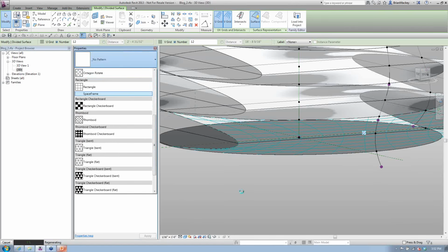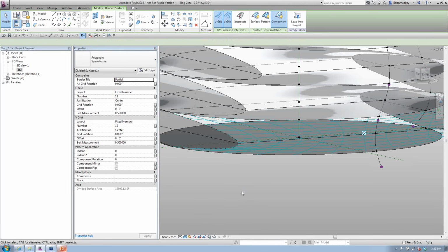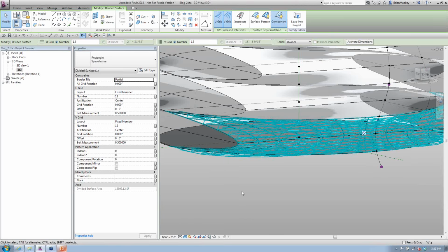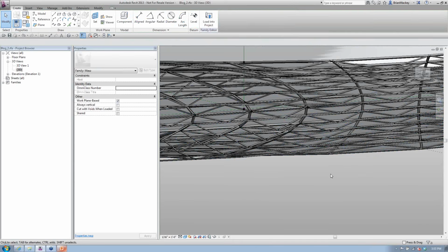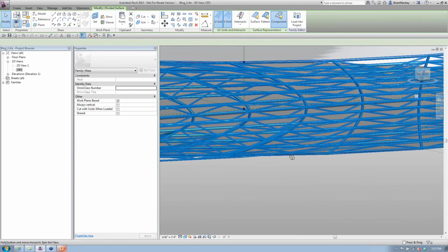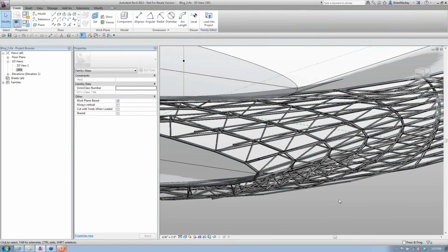So in this case, it was working with a structural engineer, and they were trying to figure out how can we take the crazy mass that the architect is dealing with and come up with a space frame option for this. So I went and created a space frame panel, generated that mass, and now you can kind of see, oh, look at that. We've got this crazy looking space frame panel associated to the face of that mass. We can play with how many times it's divided. We can play with however that space frame panel wants to look. And we can really start getting into that information.